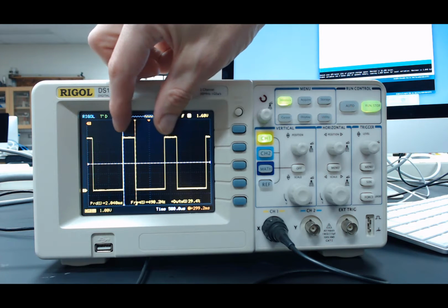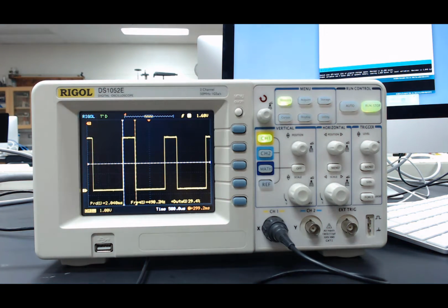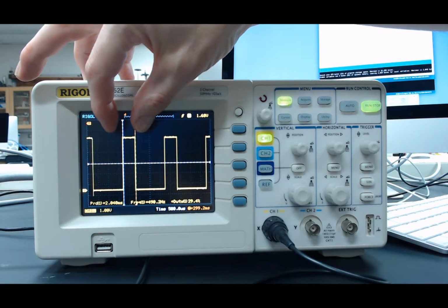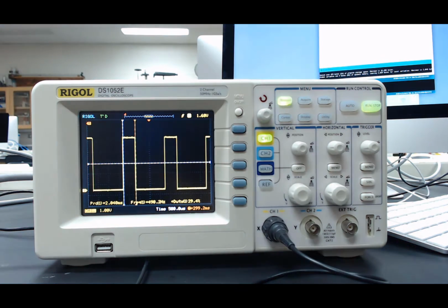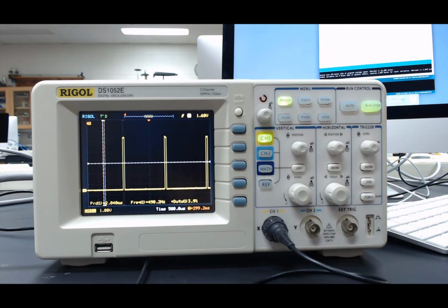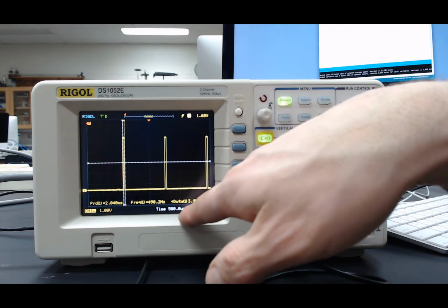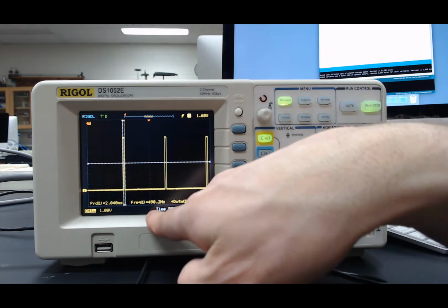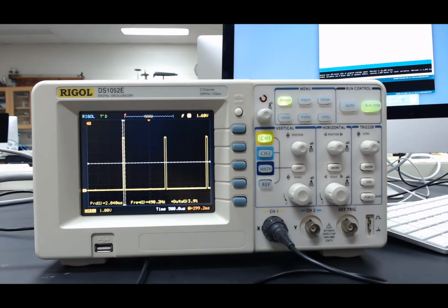And so changing the parameter in analogWrite, all that does is change how long the signal is high during each period, making it bigger or smaller. Alright, if I do analogWrite on pin green, which is digital pin 10, and specify the duty cycle parameter as 10, now the duty cycle is about 4%. But the frequency is still 490 Hertz.